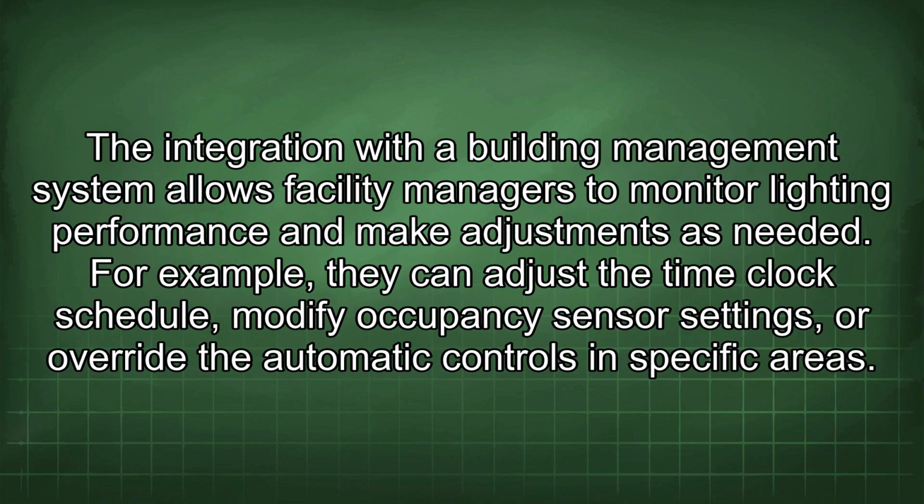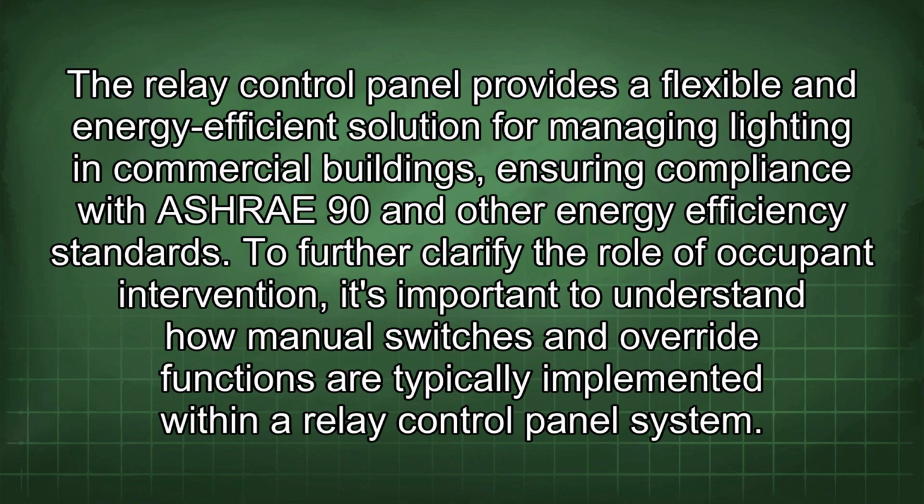The integration with a building management system allows facility managers to monitor lighting performance and make adjustments as needed. For example, they can adjust the time clock schedule, modify occupancy sensor settings, or override the automatic controls in specific areas. The relay control panel provides a flexible and energy-efficient solution for managing lighting in commercial buildings, ensuring compliance with ASHRAE 90 and other energy efficiency standards.